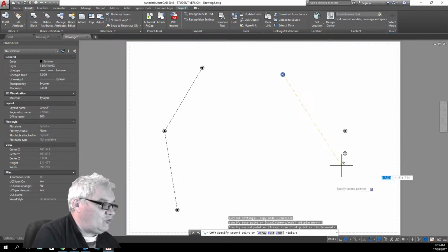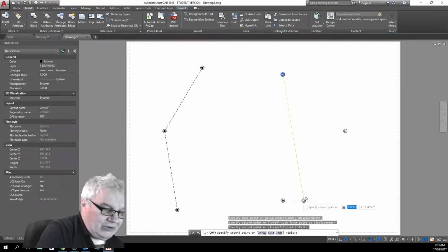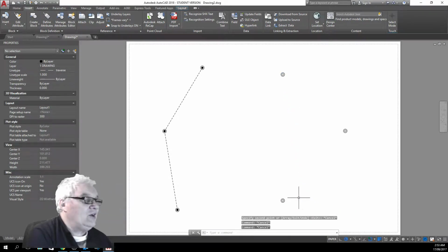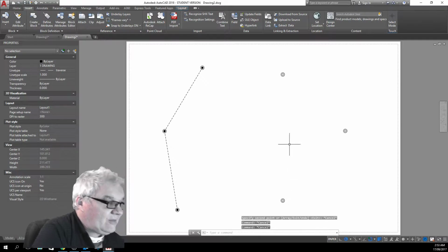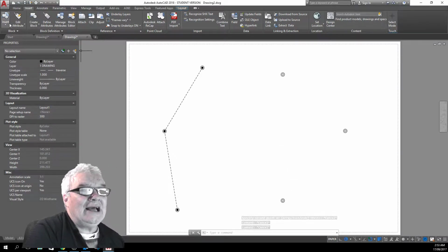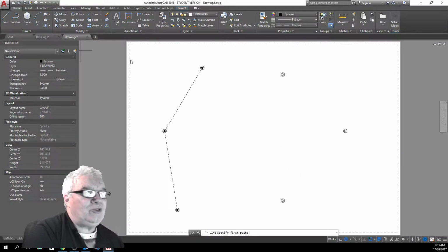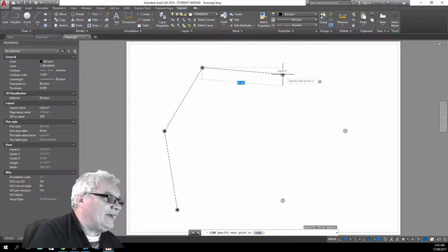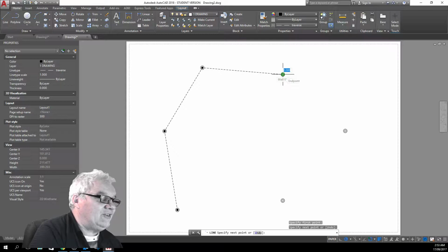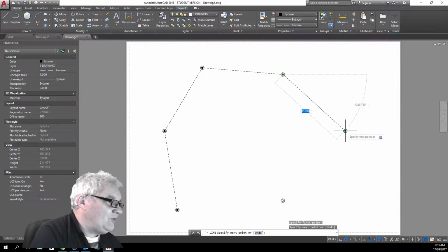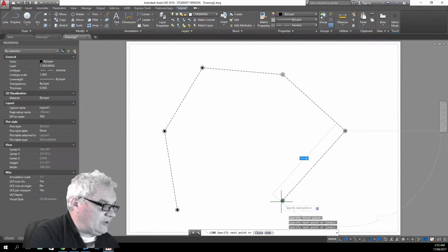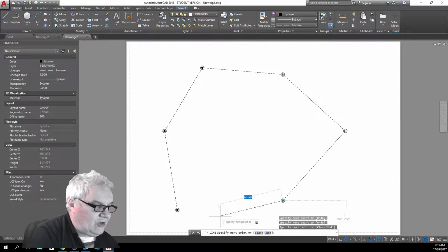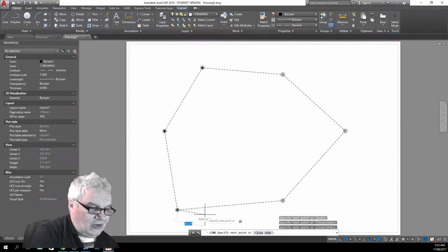These are our new traverse marks. We'll put a few of those in around the place, and then we will traverse between them, or measure and observe. We'll set up there, possibly backsight the other old mark, and measure forward like so, and like so, and like so.